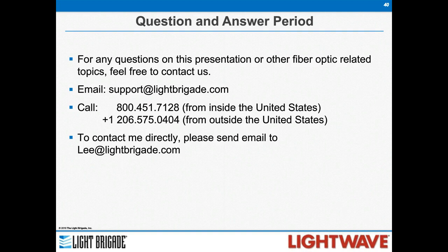So we have one question: why isn't there a standard for testing patch cords? I don't know what you mean by a standard. The manufacturers of patch cords do have standards that they use when testing their patch cords before shipping. They test for loss of those connectors. They usually do some interferometer testing to take a look at the endface and make sure it meets the Telcordia requirements. So depending on the manufacturer, they can have a whole slew of tests that they would provide to assure that those patch cords are the quality that you want and are able to achieve the loss that you want. If you're referring to test reference cords, it might be a little different, but there is a standard for testing patch cords.